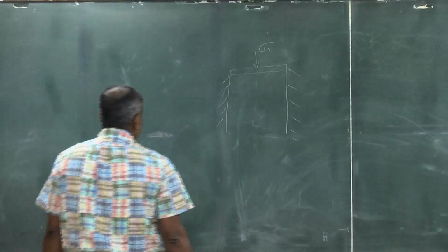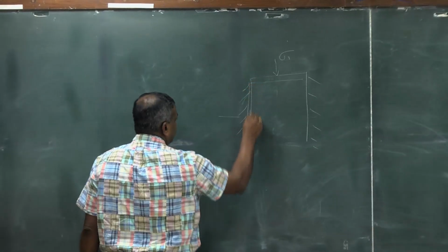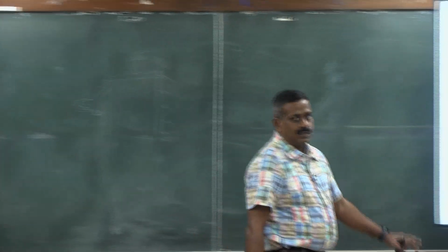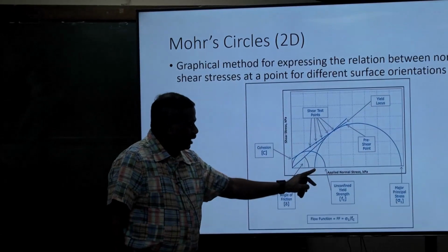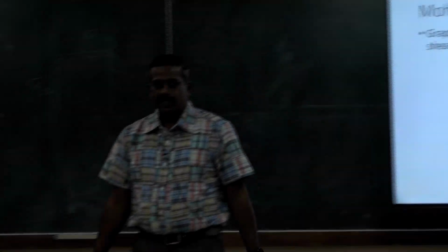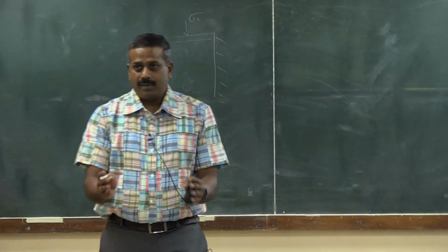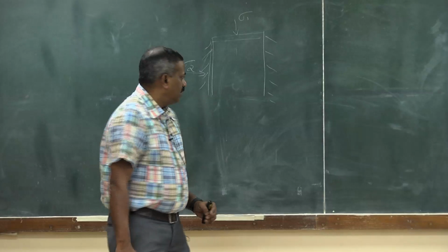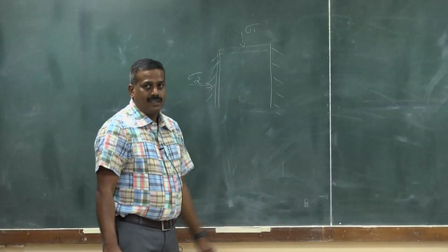The stress acting on the side walls is sigma 2 here in this Mohr circle. That will be the minor principal stress, which also helps to compact the powder. Though you are not applying any force or stress on the sides, due to the confinement there will be some stress acting on the powder.